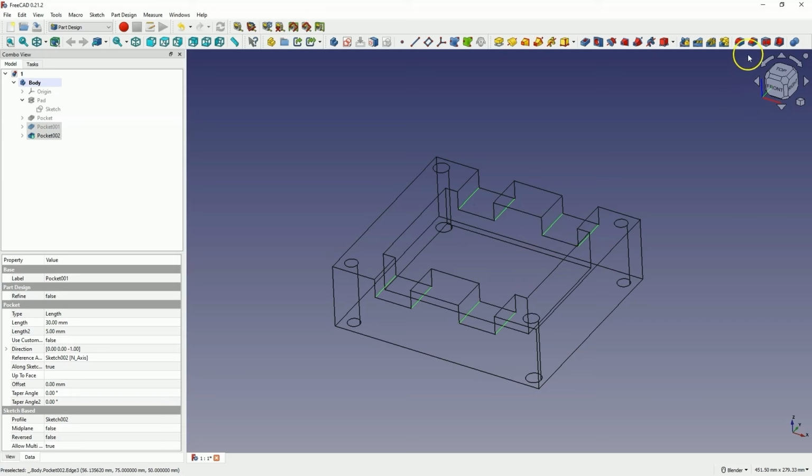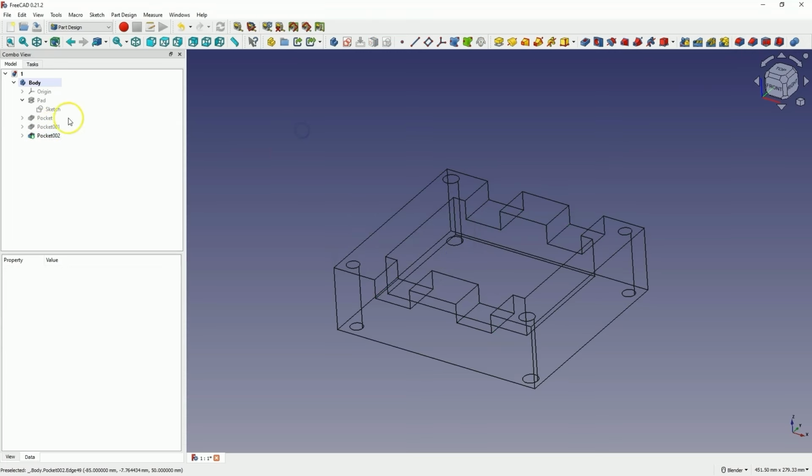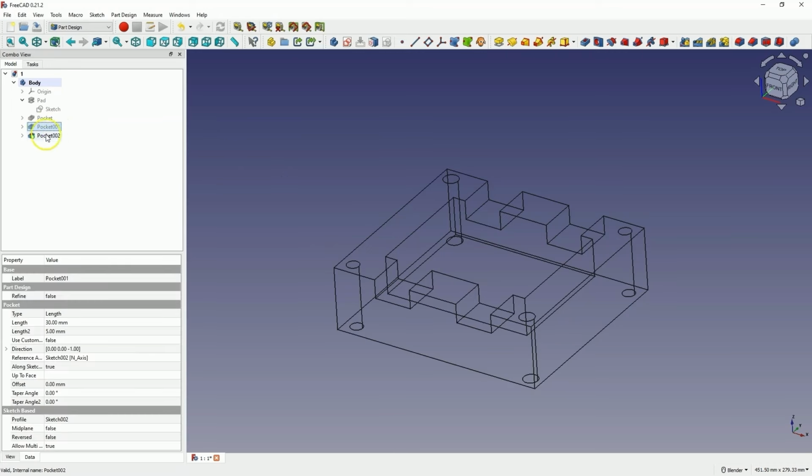We select these lines. Here we will add a fillet. Choose this command, and a warning has appeared here. I see that these two operations are selected, so I deselect them. It is possible that this operation was somehow selected, and then with the Control key, I began to select additional geometries.